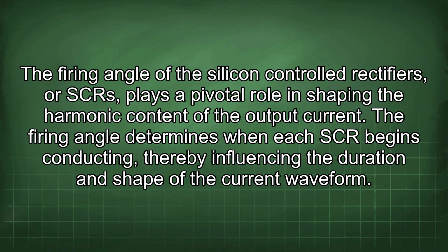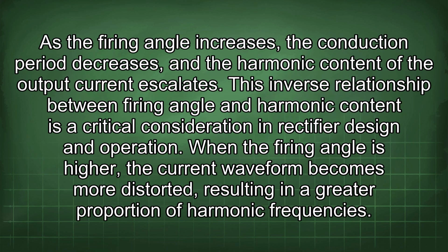The firing angle of the silicon-controlled rectifiers, or SCRs, plays a pivotal role in shaping the harmonic content of the output current. The firing angle determines when each SCR begins conducting, thereby influencing the duration and shape of the current waveform. As the firing angle increases, the conduction period decreases, and the harmonic content of the output current escalates.